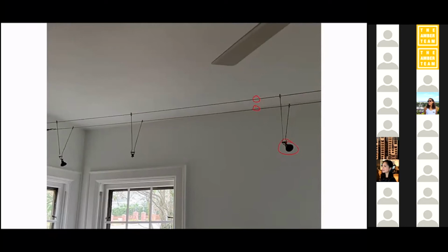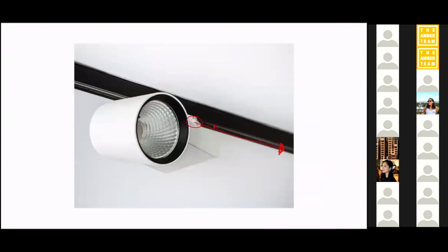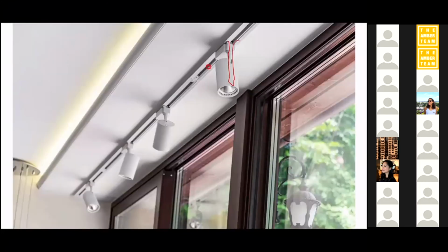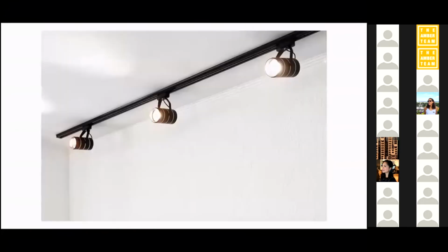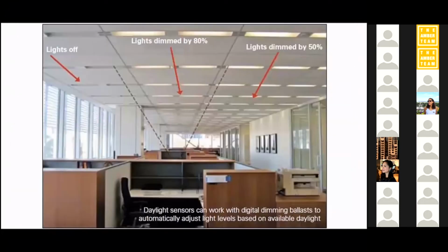And that way, if I am touching this wire and this wire, I'm unlikely to create a path that becomes a short circuit, because anytime you connect the hot to the neutral without going through a resistor that's intended to regulate, to throttle the amount of power going through it, then the whole thing heats up, and eventually you blow a fuse, hopefully, in the best case scenario, and the worst case scenario is you start a fire or electrocute someone. We'll get to that in a little bit. Well, I'll talk about it now. We have lots of reasons to dim.